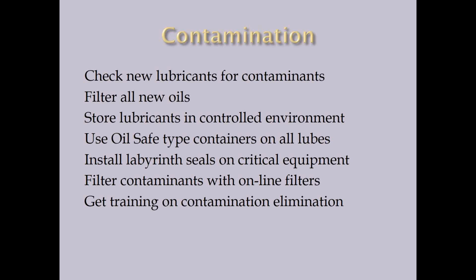If you look at our website, we have a lot of filter carts, filter trailers, where you can take a filter cart up to a hydraulic unit or a gearbox. We can hook on the drain line, filter the oil, put it right back in the unit. We can keep those moisture and particle levels way down in the gearbox and extend that life 3 to 6 times. Get some training on this contamination elimination. You have to get your people trained that are doing the lubes.